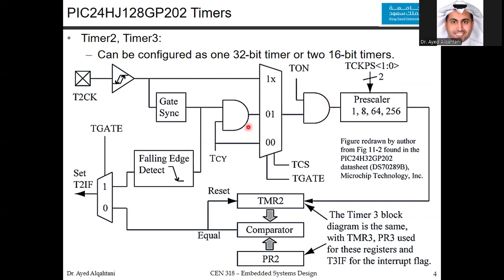Now, also, it's good to look at this AND gate. You can see that if for some reason you have an internal clock and also you want to take the external clock, it's kind of a mixture between them. You just take the AND gate to generate a clock that is at the intersection between these two clock sources, but this is not usually a good option. We usually choose the internal. Sometimes we use the external, as we will see later.